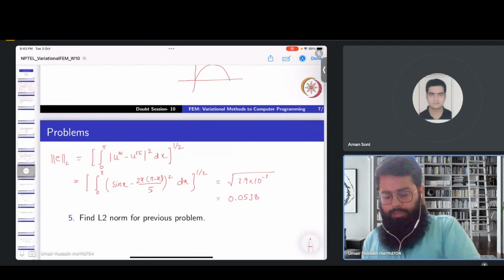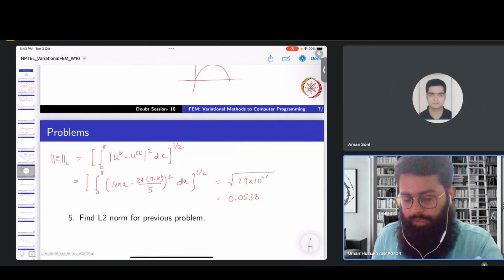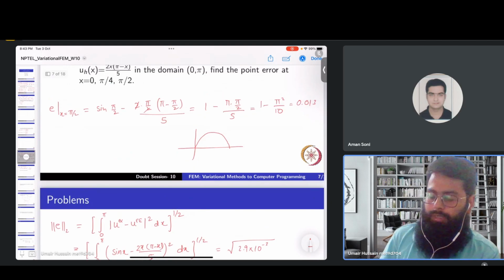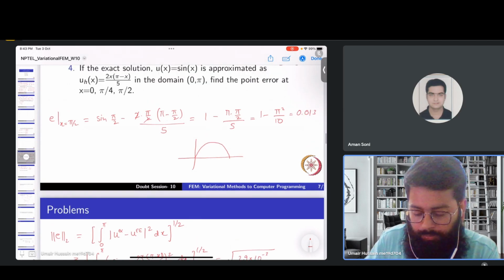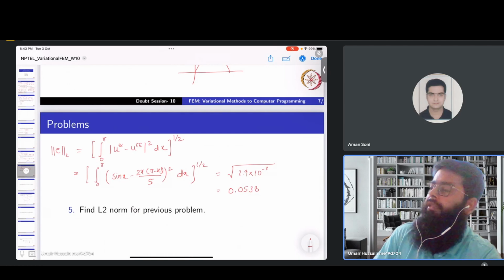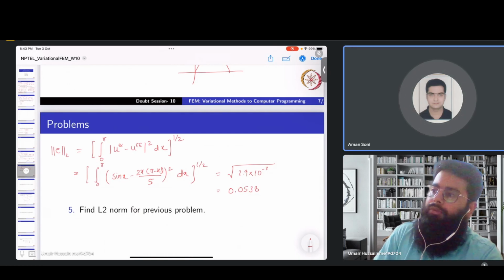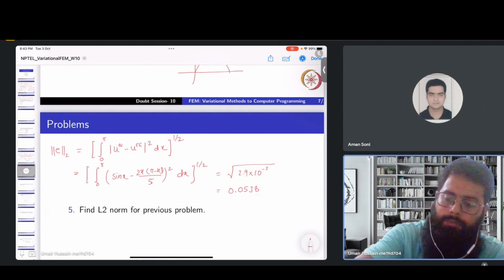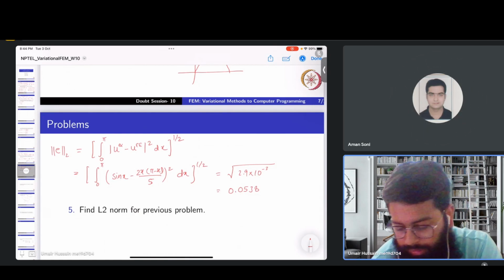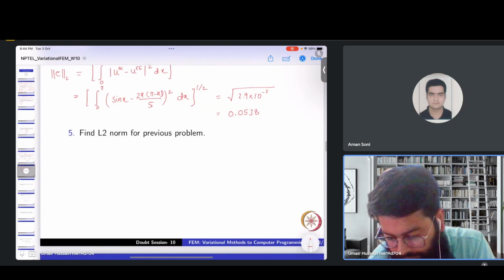So this gives us a quantification of error across this domain, or if we do it for particular cells in an FEM problem. So this gives us an estimation of the combined error in the entire cell. This gives us a judgment on what is the situation of error in what part of the FEM domain, and this is useful for refinement.